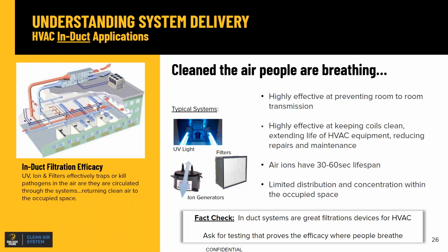All right. We are going to very briefly talk about Big Ass Fans ionization options compared to an induct system. The easiest way to think about it is, number one, I need a high concentration of ions to make an immediate or rapid impact. And two, I need them everywhere, all right? A lot of classrooms may have one supply register in the far corner, one return register in the near corner. If you put an ion device in the air handling unit, you may get decent ions over there by the supply register. But you're not just trying to keep the 3 students under the supply register safe, you're trying to keep the whole classroom safe.